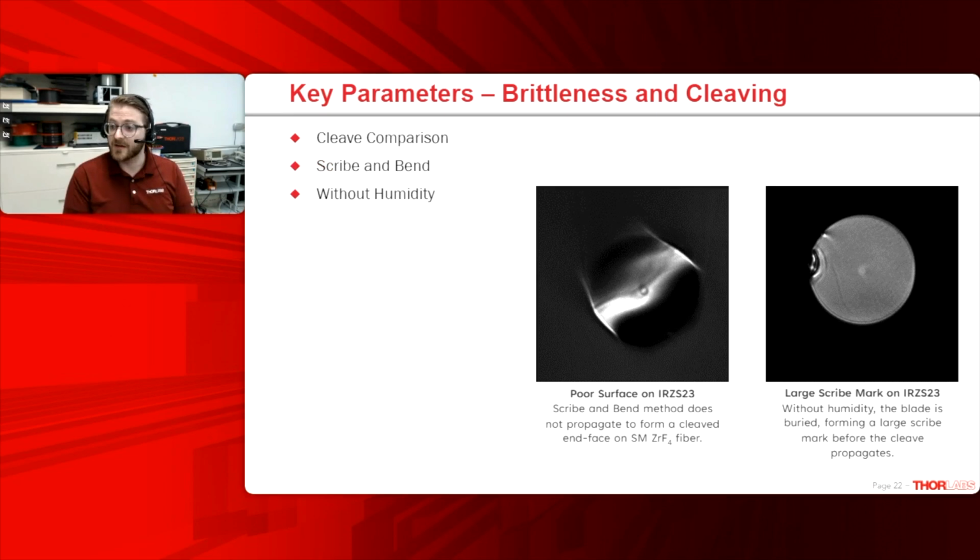On the right here, I do have an image of a fiber where I delayed adding any humidity, and I add that just by exhaling on it, just like breathing on glasses to clean them. And as you can see, this scribe mark is huge. I had to eventually breathe on it just to make sure that I didn't damage the blade.